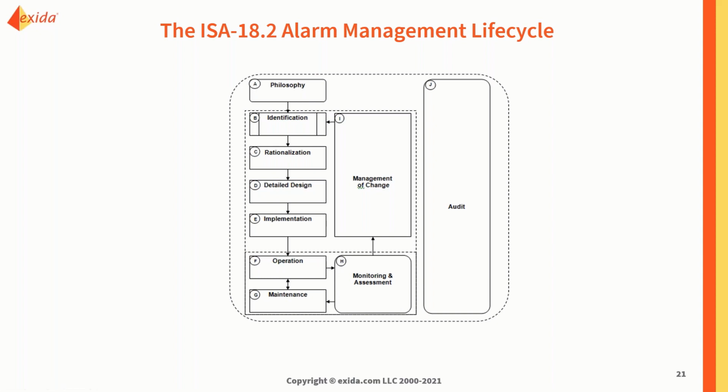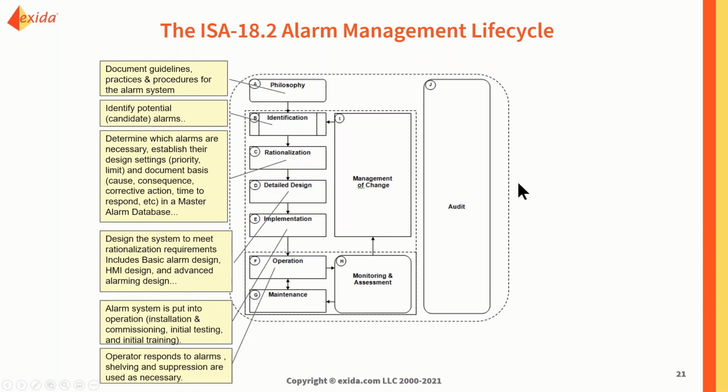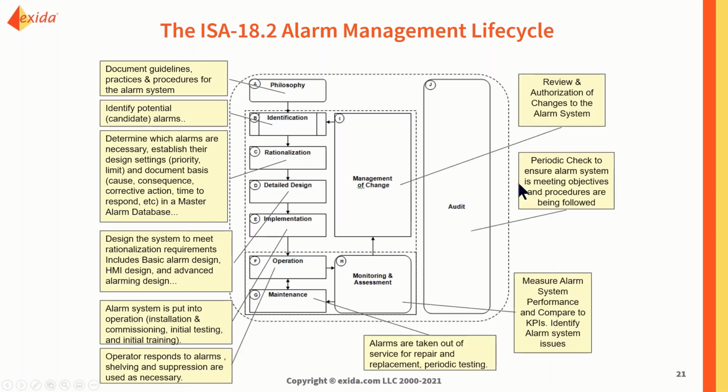And in the OPC standard, there is a strong reference to the ISA 18.2 alarm management standard. ISA 18.2 is specifically about alarm management. In fact, within the OPC standard they use a lot of the terms defined within the ISA standard, and they align with the concepts in ISA 18.2. So this is an overview of the whole life cycle of the ISA 18.2 standard.